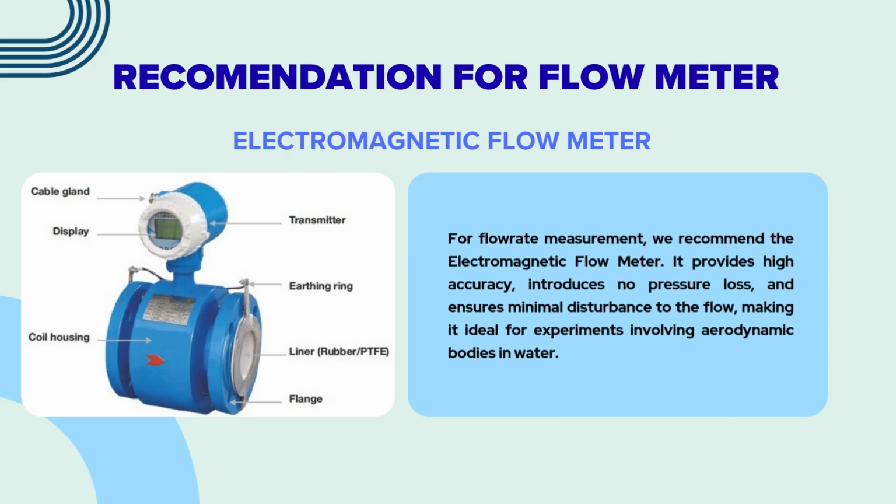For accurate flow rate measurement in our experiment, we recommend using an electromagnetic flow meter. This device operates based on Faraday's law of electromagnetic induction, allowing it to measure flow without any moving parts. It offers high precision, introduces no pressure loss, and does not disturb the flow, making it ideal for aerodynamic body testing in a water channel. Its non-intrusive design also complements the transparent acrylic setup, ensuring clear observation while maintaining reliable performance under various flow conditions.